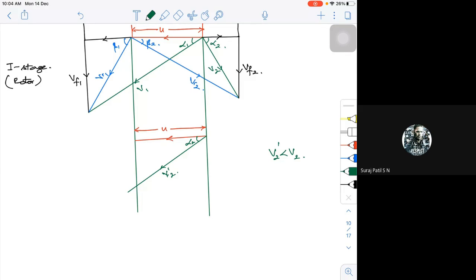So the friction factor may be 0.95 times or 0.98 times. A smooth blade or a new blade will have a very small amount of friction, so the carryover velocity is much better. Ideally speaking, that's why we prefer very smooth or clean blades. So that's one requirement of your blades.